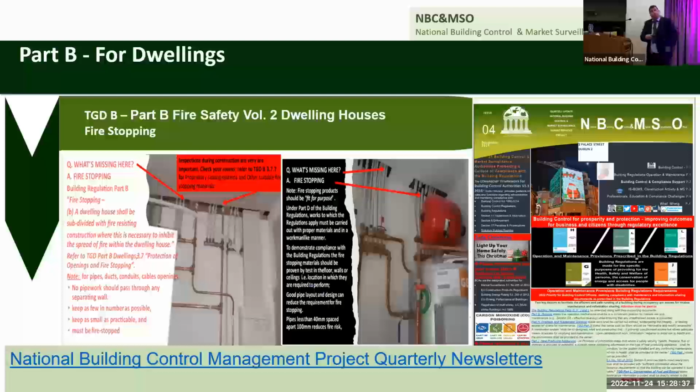And these are pictures in dwelling houses where the plumber has put all his pipes up. And these are in utility rooms, one of the highest risk rooms in your house. And if these are metal web joists, that fire is going to spread through it. Undesigned, you're not going to get your 30 minutes of load bearing, if there's a sealant, in two-storey houses.